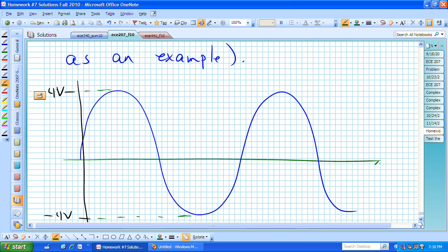But what we actually find is that because of the light load, we can't do that in this case, and we're actually going to be clipped at 1 volt. Then our voltage will go up, get clipped at 1, come down, and get clipped at -1, go up again to 1 and get clipped.